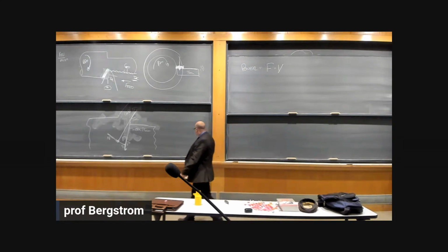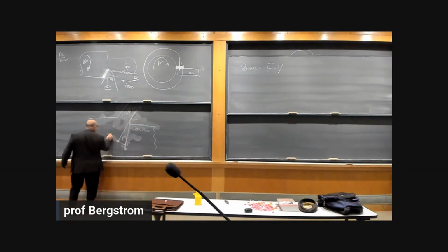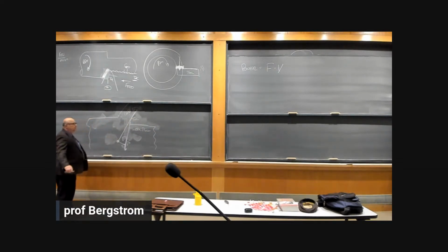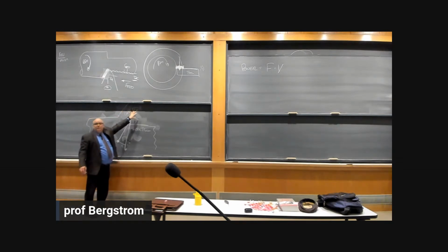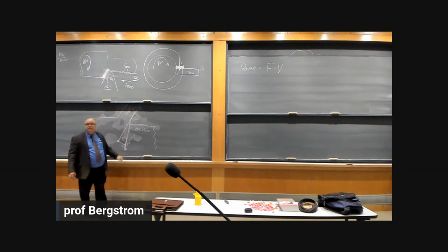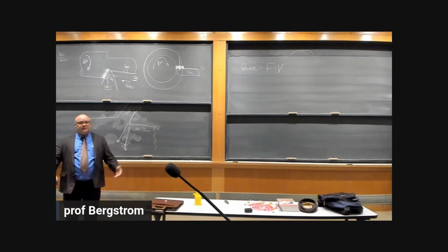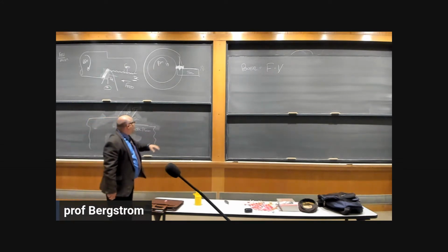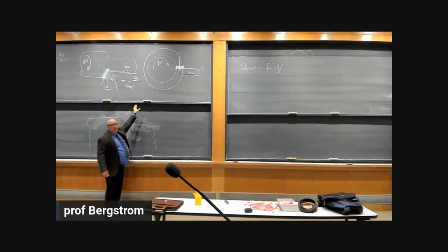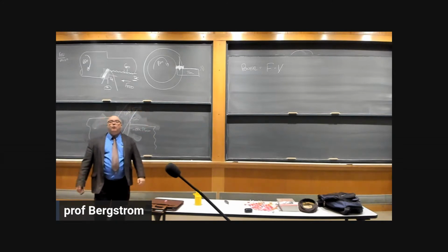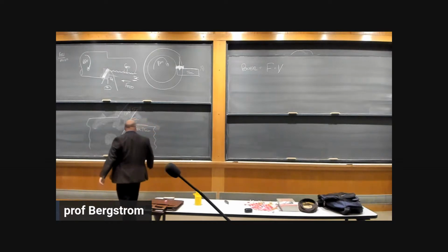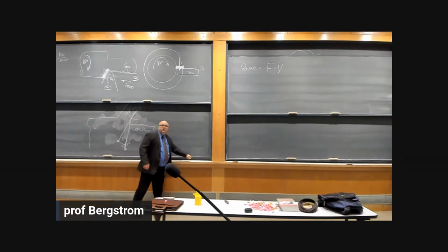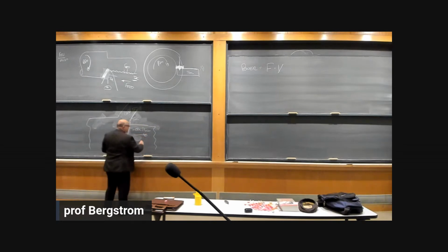Now, if our operation is in steady state, there's no acceleration. That now describes the forces acting on the chip, or on the tool, or on the workpiece. Right? That total force is the force. But power equals force times velocity. We don't know the velocity of the chip. What we do know is the velocity of the chip is not the surface speed. So our surface speed is in that direction, right?